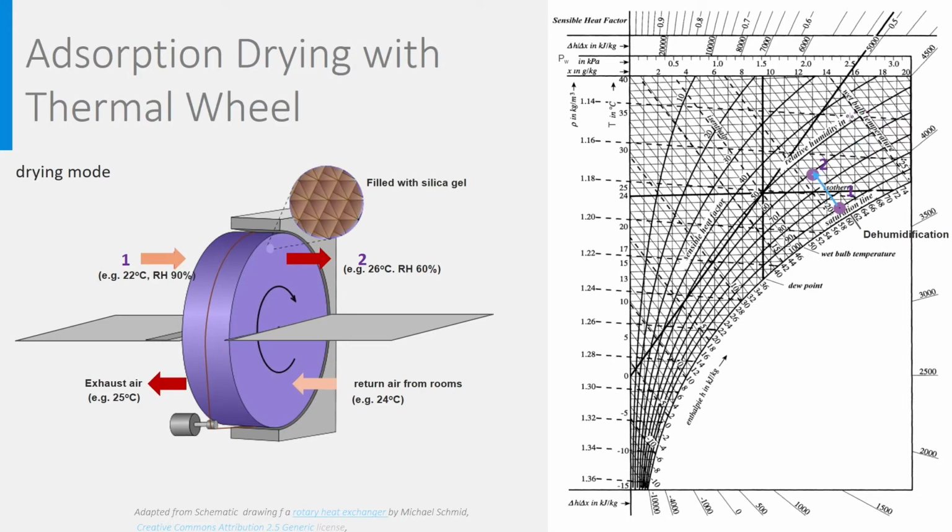It is also possible to place adsorption material like silica gel in the beehives, enabling drying of humid air by adsorption, which is an adiabatic process leading to drier and hotter air. During drying, latent heat of evaporation of water vapor is released in the air, increasing its temperature.